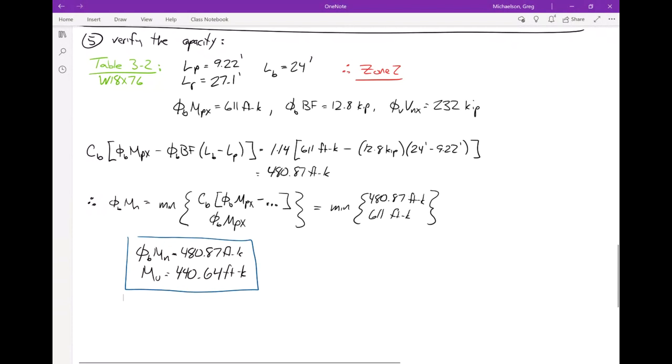So 0.1 kips per foot, not 0.01, but in pounds. What is it in pounds? There's a reason why I'm saying pounds. If it's 0.1 kips per foot, it's 100 pounds per foot. Now, we assumed 100 pounds per foot. What is the actual weight of the beam that we selected?